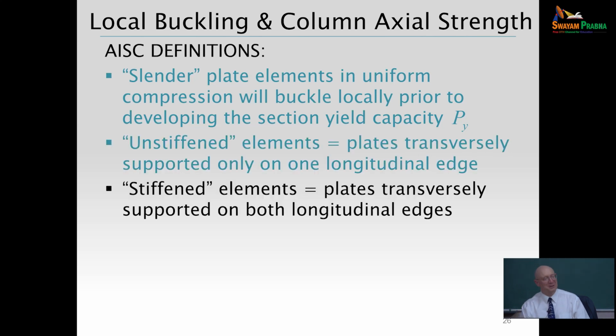Okay, and stiffened, that's where I was going there all along. That would be like your web in an I section. Both edges of the web are prevented from lateral plate bending movement by the flanges, or restrained from lateral plate bending movement. So we have slender plates, unstiffened plate elements, stiffened plate elements. That's AISC's definitions.